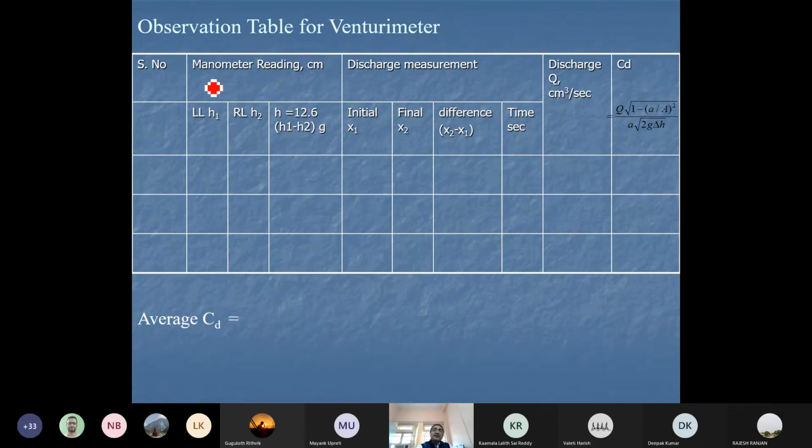And then I will provide you observations for the left hand head, that is basically the inflow side of the supply line, and the right hand head, that is basically on the venturi throat or just after flowing through the orifice meter. So these are two heads measured in this system by using a U-tube manometer, and both the observations are there. You can find out the delta H.